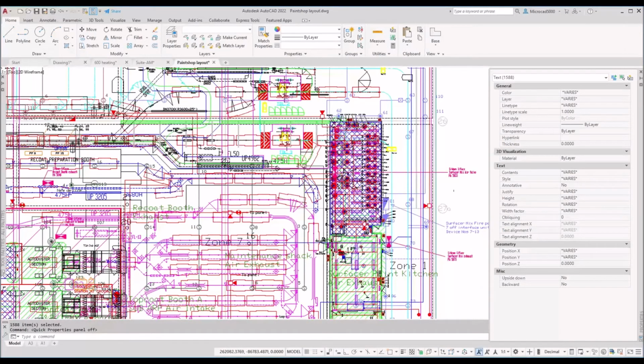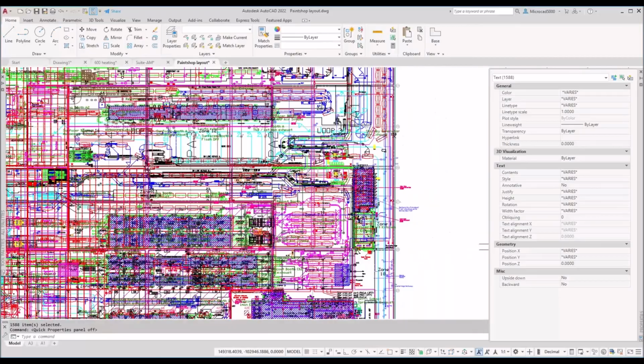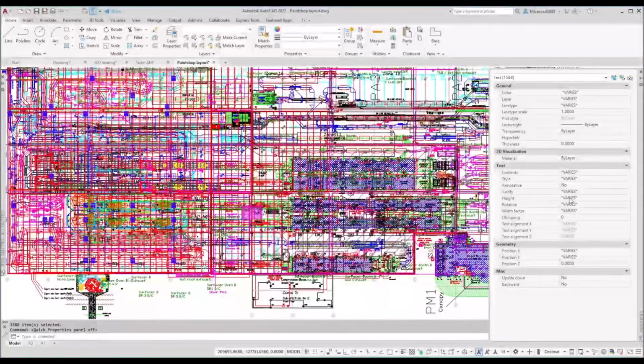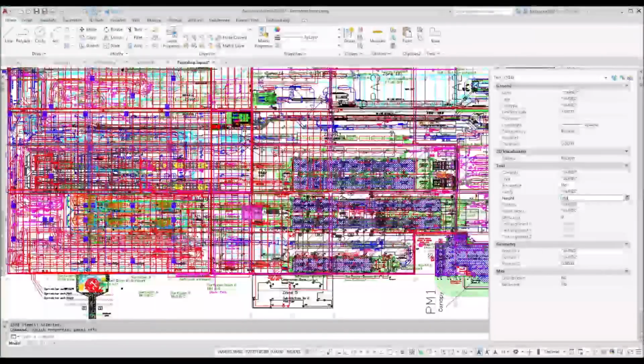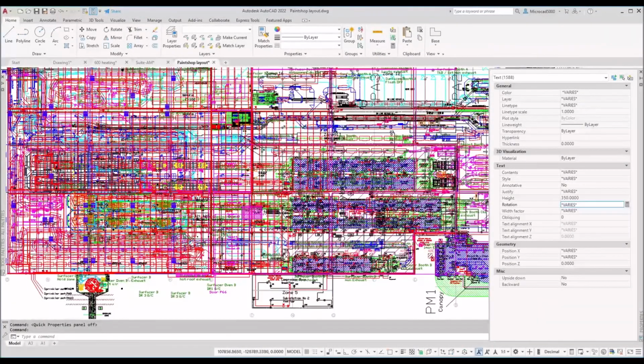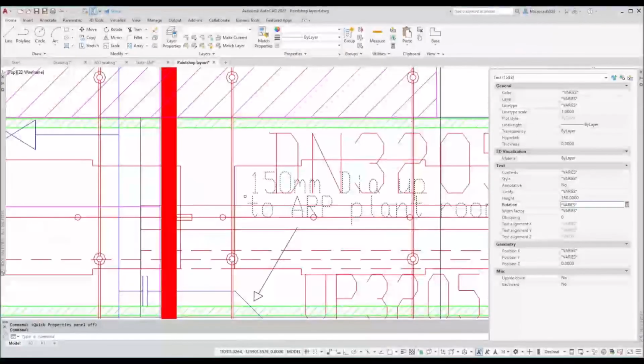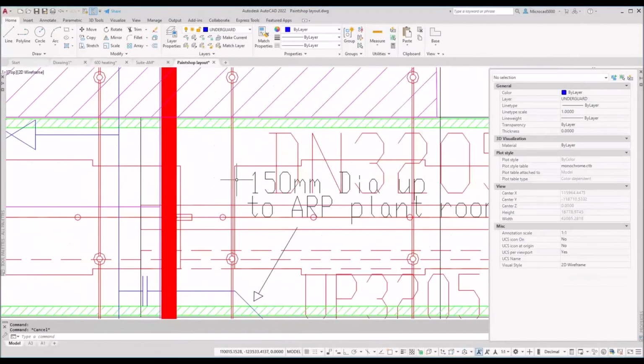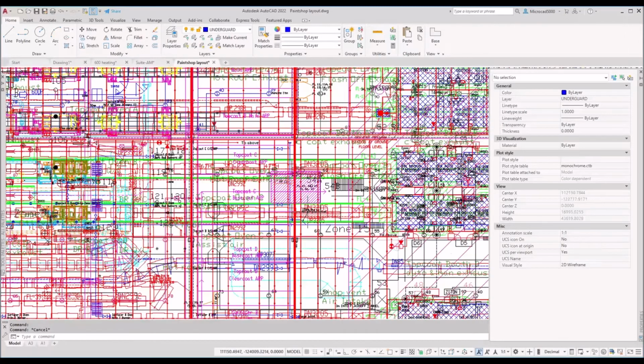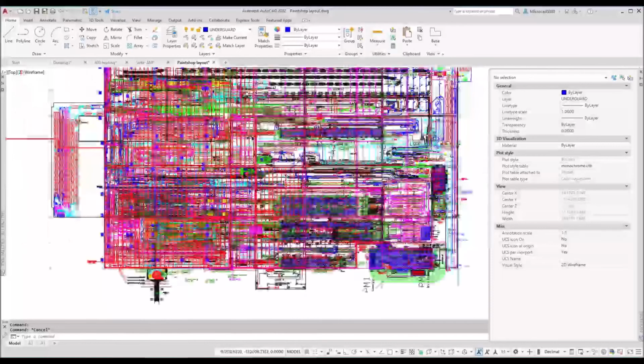Now in the properties box, I can go and select the height there where it says varies and type in, I can make it all 350. Hit the enter key and it goes across the drawing and that's it. Job's done. As quick as that. Thousands of pieces of text. Now, to do that manually is an unthinkable task, isn't it? An unthinkable task.